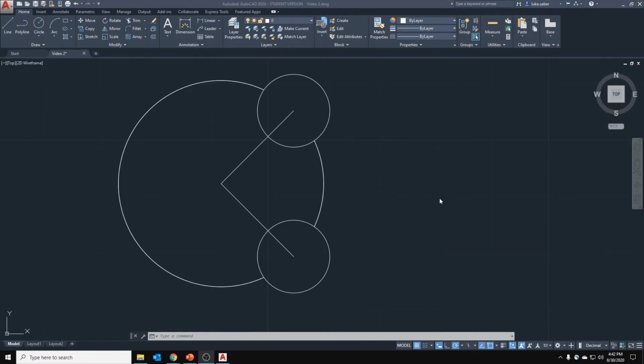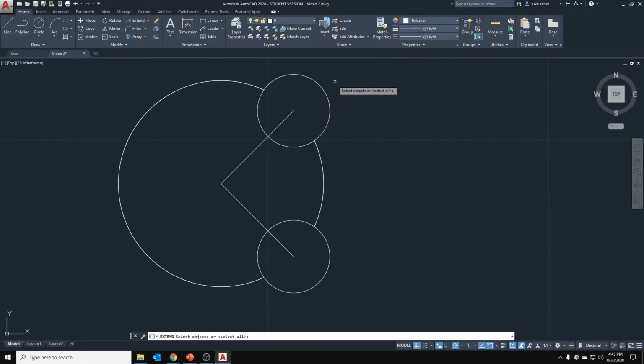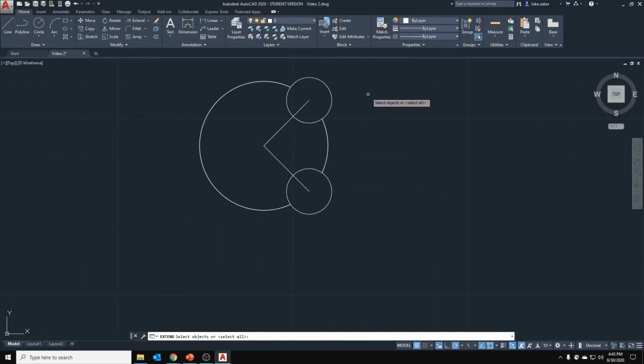Okay, so that's pretty much the biggest part of trim here, but you see there's a little arrow down here. A little up here, I guess. Then in this menu, it'll have options because a lot of these tools you can see fillet, array. See under the draw menu for this one, there's a little arrow. That means that there's more options that are related to the same thing. So this one is extend. It'll take a segment and it'll extend it to the next bounding area.